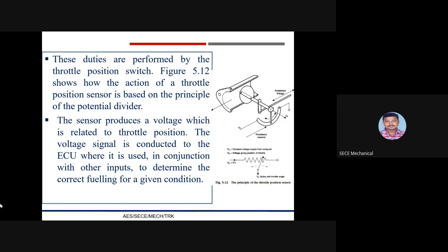Based on its construction, there are three types of throttle position sensors. They are the throttle position sensor with built-in end switches, also known as closed throttle position sensors, the potentiometer type, and the combination of both types of sensors.